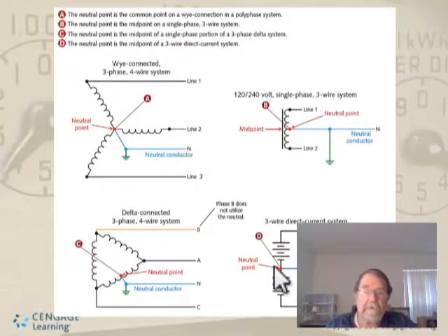There should be no potential between, if you have a chassis ground and then you have the neutral system, you shouldn't have a voltage between those two. If you took your meter and put it between a case where you put your ground, your green wires, and your white wire, and you put your meter on the terminal block where all your neutrals connect in your service box, or even in your feeder sub box, you shouldn't have a potential. If you do, you've got a problem.